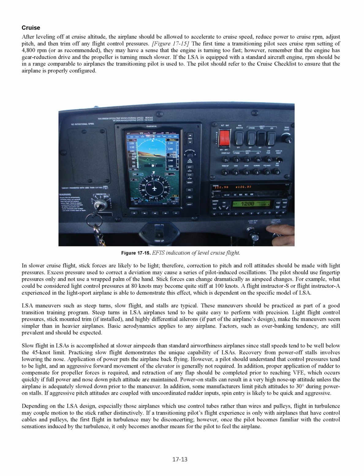If the LSA is equipped with a standard aircraft engine, RPM should be in a range comparable to airplanes the transitioning pilot is used to. The pilot should refer to the cruise checklist to ensure that the airplane is properly configured. In slower cruise flight, stick forces are likely to be light, therefore, correction to pitch and roll attitude should be made with light pressures. Excess pressure used to correct a deviation may cause a series of pilot-induced oscillations.